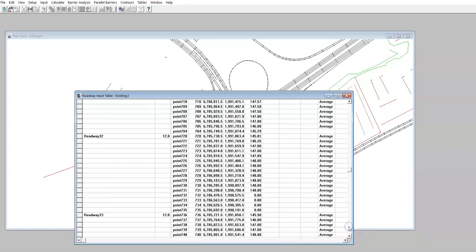It really helps to review all this just to make sure you have reasonable data. Like for instance, in this place, we have zeros. So we still need to enter elevations for these areas. So for these, we need to go back and review the MicroStation contours, see what got left out, and we might need to carry this elevation across to those points if we don't have topographic data for these points, or somehow obtain data to completely populate this data table.